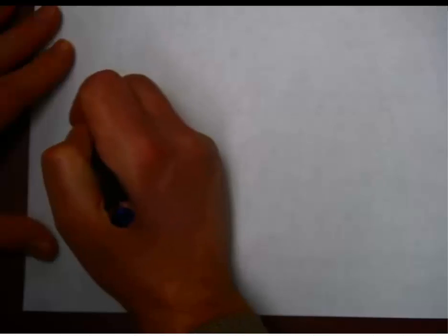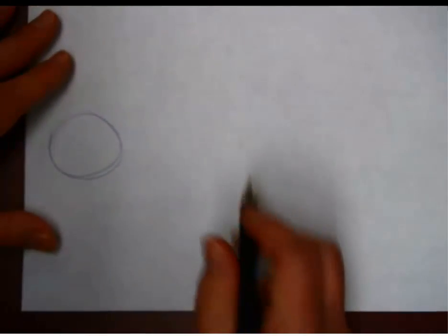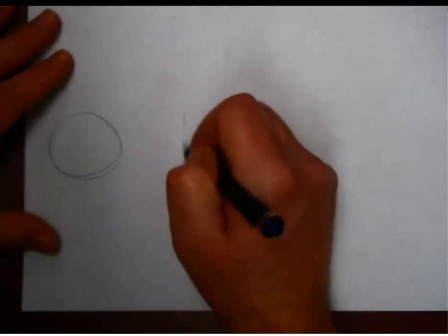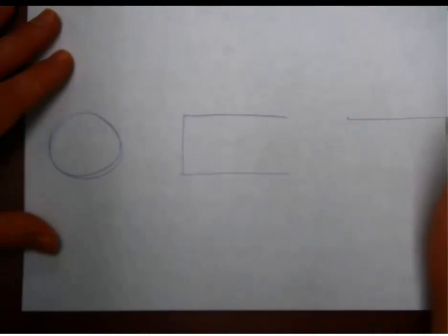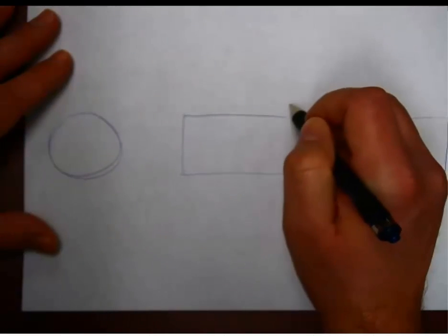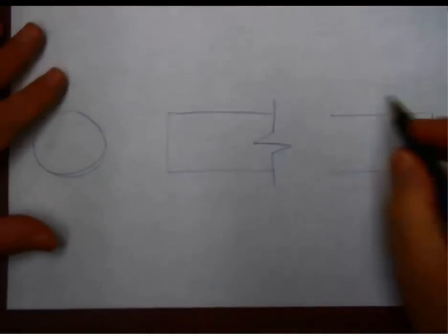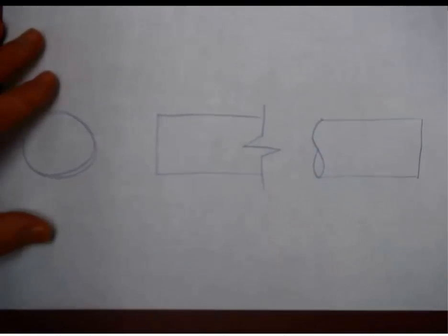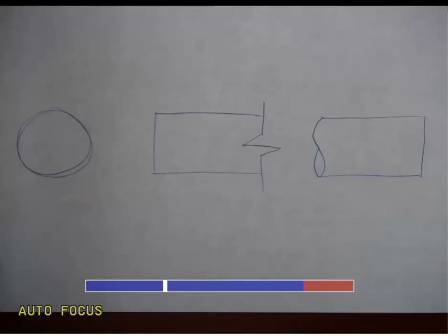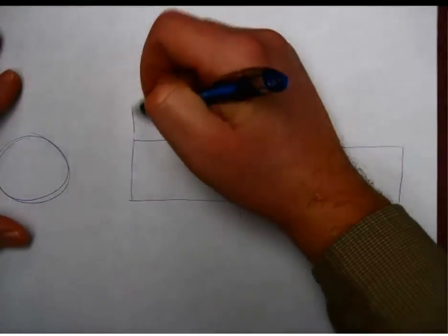So what I want to do instead is I want to zoom in and I want to get that at a larger scale. So maybe I can get the circle shape a little better, and then on the rectangular shape, the longitudinal view, I am going to break it. So I might have some break symbols like that. If it's a cylinder, you'll often see something like that for a break as well. Hopefully that looks familiar to some of you. And then when I'm dimensioning it, whatever the overall length is,